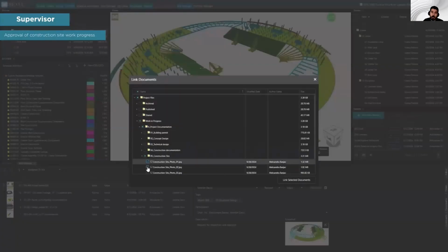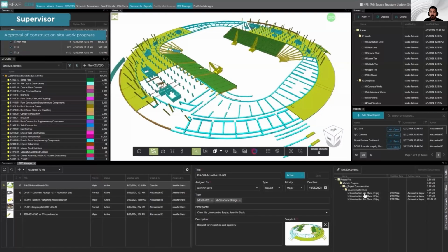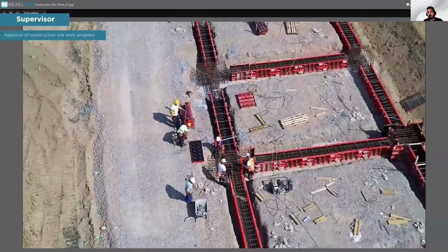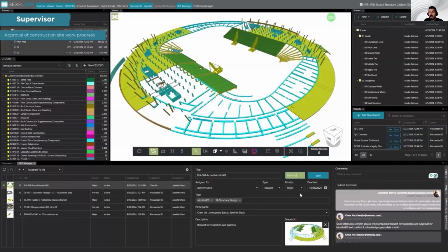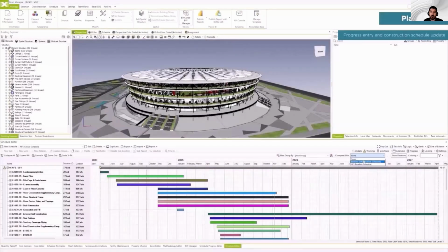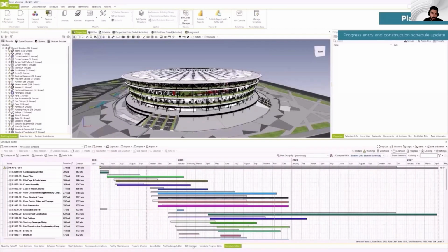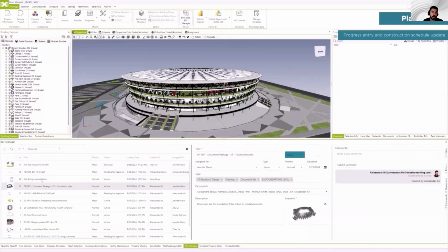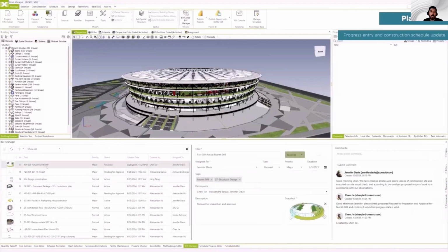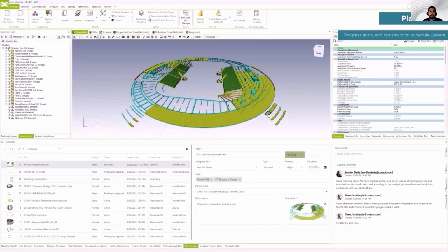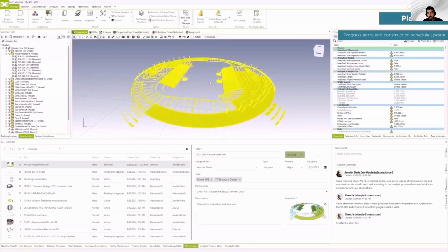Then we can come up with the point cloud and overlap what you actually reported as completed. You can attach pictures for the works that were completed. Everybody could go check it. The supervisors could confirm this, and then we can populate the progress into Bexel Manager and run the calculations and see what is the earned value, what is the planned versus actual analysis, so we can have key project indicators in real time, and we can validate all the input data very simply.